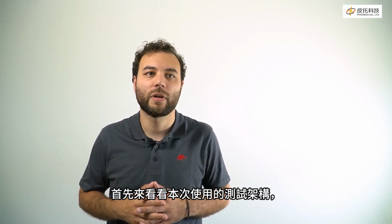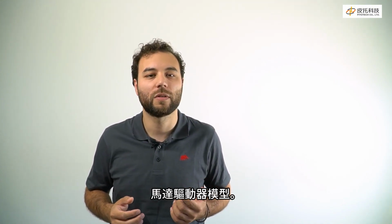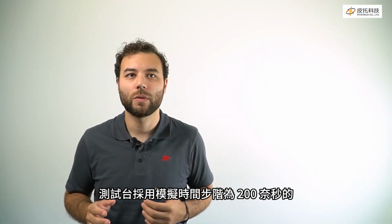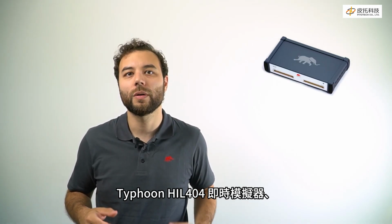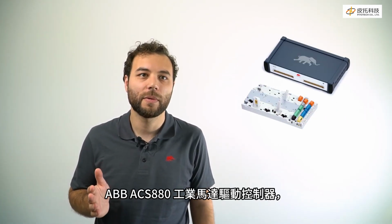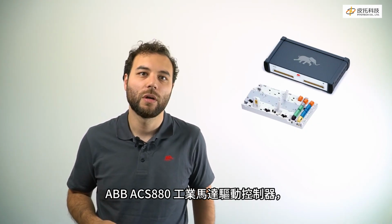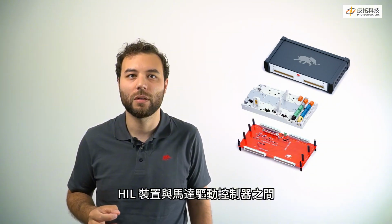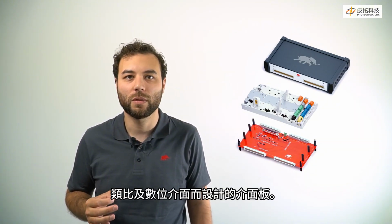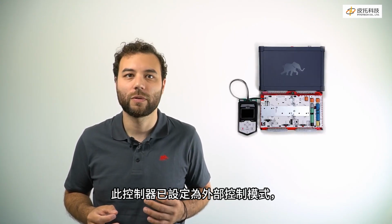Let's take a look first at the setup we'll be using and then at the motor drive model that we'll be simulating. Our test bench will use our 200 nanoseconds time-step Typhoon HIL404 real-time simulator, an ABB ACS880 industrial motor drive ECU, and an interface board specially designed to scale the required analog and digital interface between the HIL device and the motor drive controller. The ECU is configured for external control with factory macro enabled.